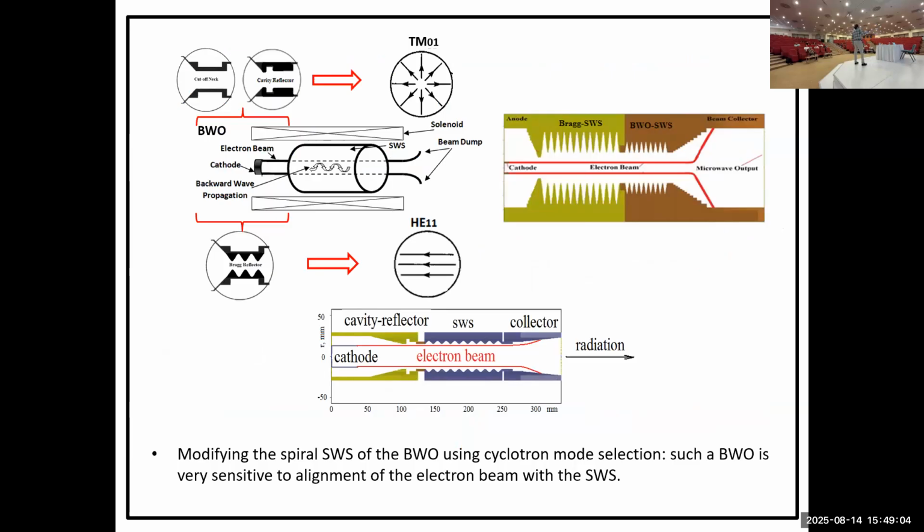Okay. Another way of reflecting is using what they call a Bragg reflector. And I think you guys are familiar with the Bragg reflector in other contexts, but it's basically a periodic structure, right? And this is optics and fiber optics. Yes, exactly. They use Bragg reflectors a lot on the small cavities. So a Bragg reflector is a periodic structure. Somehow you design it by having this periodic structure. The backward wave TM01 will be reflected toward the output or toward the antenna as a Gaussian beam.